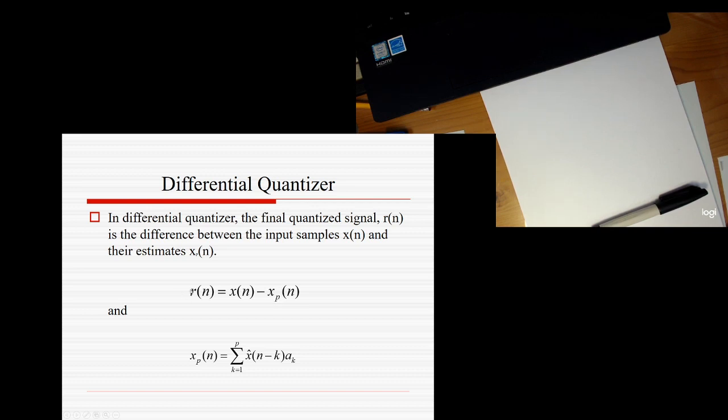So we can get a residue. This is more like a deviation signal, so here maybe residue. Here the prediction is based on previous data. You can see it is based on S hat n-1, S hat n-2, multiplied by coefficients. This one is based on the decoder. It's not based on the previous S of n, not on the previous signal. It's based on the decoding signal.